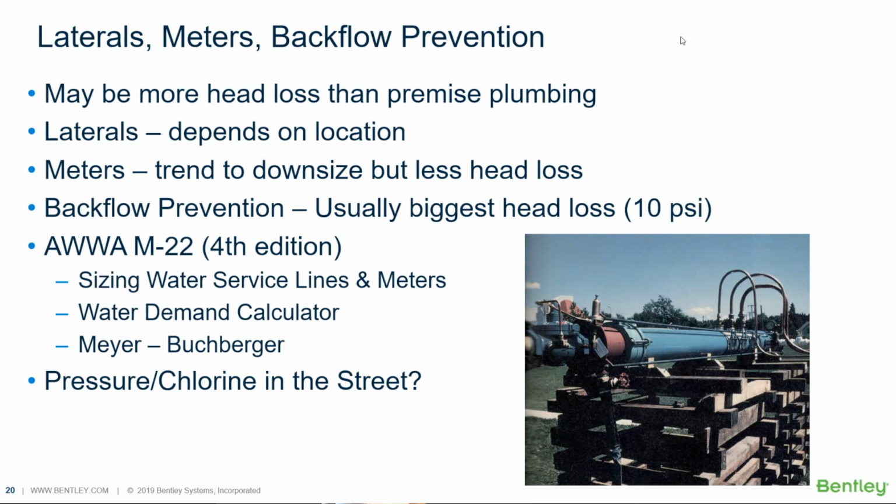It may be 58 psi if you go out there and check it today. Tomorrow, maybe 45, or at 2 o'clock in the morning, it may be 71. Or maybe 5 years from now, when there's growth, it may be 38. Or they may move a pressure zone boundary. It can change. And this is one of the real challenges, even more so in fire sprinkler systems, but also in building plumbing: what do we use as the source pressure?